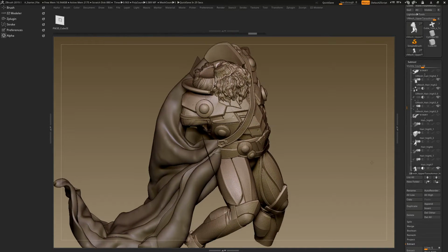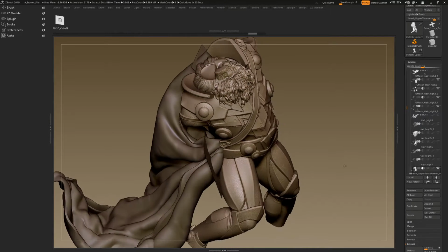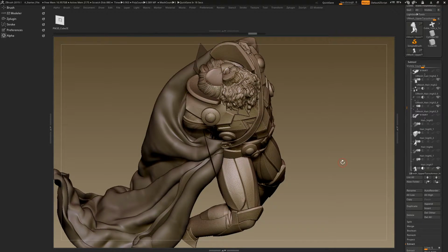If you make it too tight, now I can make adjustments to it depending on the size of the model. If you make a part with no tolerance, that's what we refer to it as. It's not space, it's tolerance. Exactly. If you make parts with no tolerance whatsoever, if there's any error, the parts won't go together. They will bind.